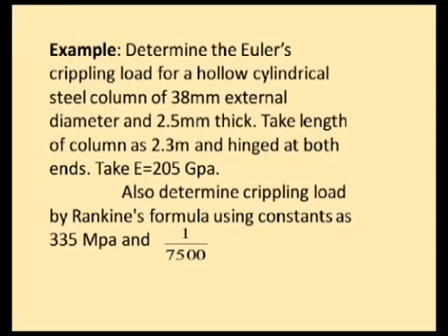So, if I want to find the value of k, then again this computation of moment of inertia becomes essential. So, we should be familiar in computing moment of inertia of different sections, which we have already studied in several units or topics. So, this is the problem wherein we will be comparing the crippling load by Euler's formula as well as Rankine's formula, so that we can have an idea of both the formulae.